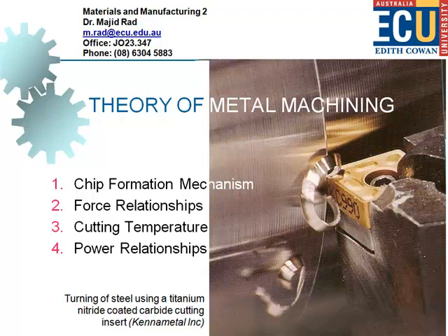And the reason for making the insert is that the quality of the cutting tip is of high quality. It is made in a way that it can maintain its stiffness and hardness at elevated temperatures. And if we want to make the whole cutting tool just by making use of this material, it's going to cost us a lot.